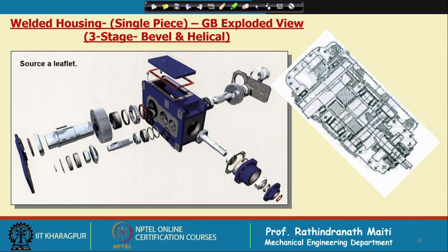to show what the gearbox is, what the reduction unit is, and what the components are there. Design of such a gearbox involves the design of helical gears, the design of shaft, design of bevel gear, design and selection of the bearings, then calculation of how much lubricant is required, all such things. For refined calculation you need to also consider how much heat generation, etc.